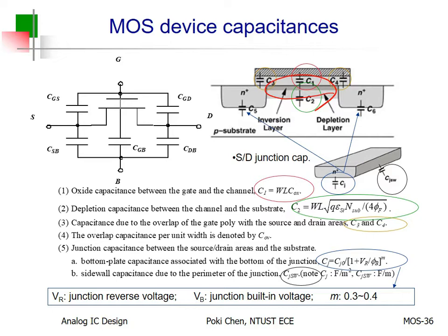That is the main focus for capacitive MOS operation. Okay? And humankind tried to increase C-ox, as I mentioned already, because it can help us to reduce VTH, blah, blah, blah, to speed up the operation.